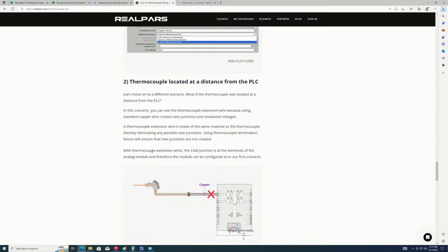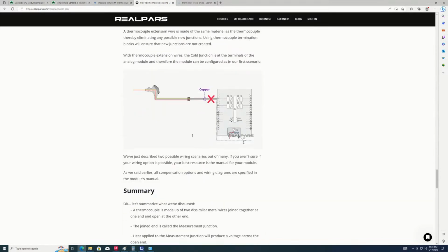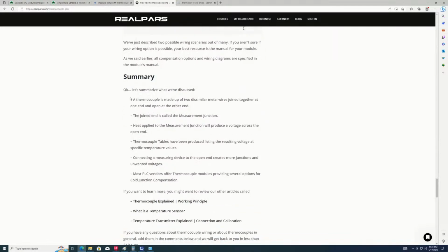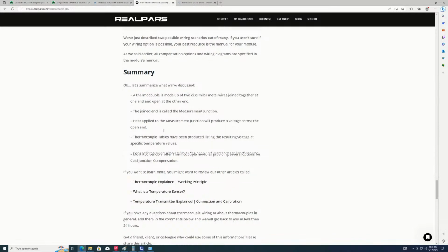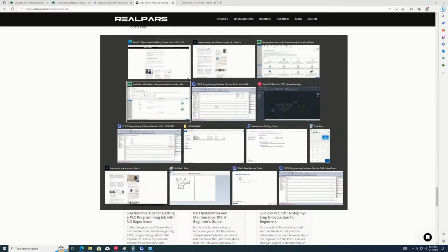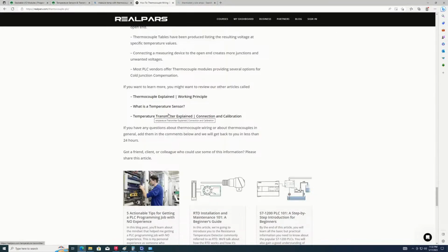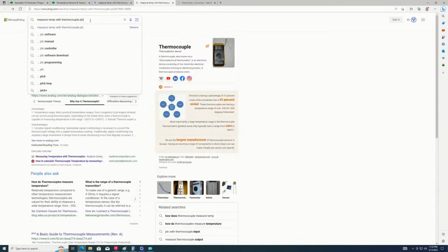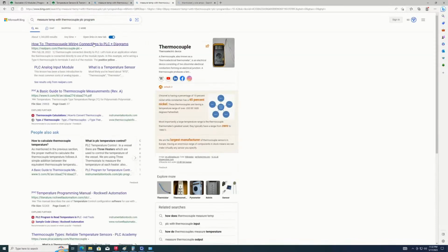New junction not created. Don't extend the cables on your thermocouple. They're not speaker wires. It's done by resistance, and if you make it longer, the resistance is more, and it'll read wrong.